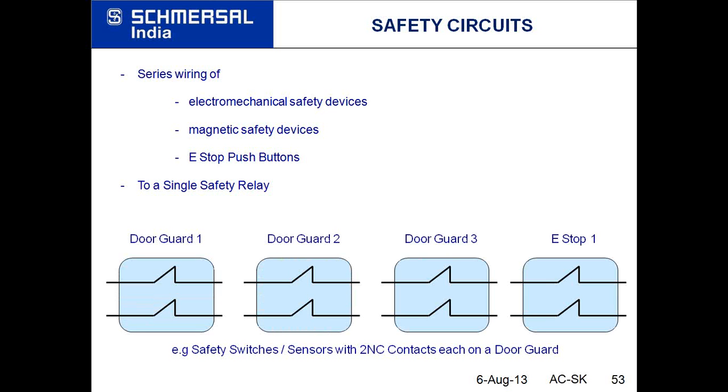But if we use a single device on a single safety relay, then we can achieve performance level E, or control category 4.